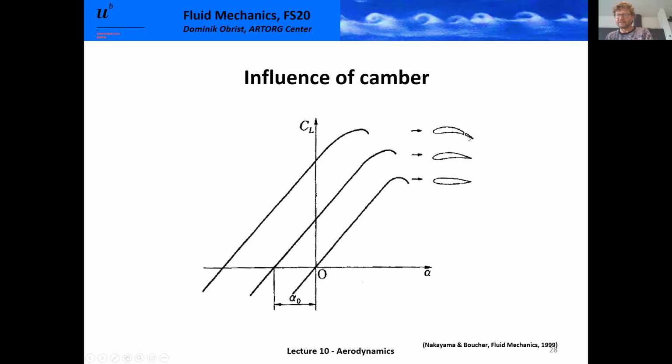And the flaps here, you can see them in commercial airliners. If you sit above the wing and look out at takeoff and at landing, they will put out the flaps, and it's not so much to increase the size of the wing, it also does that, but in the first place, it increases the camber. They put out the flaps to increase the camber to locally increase lift. It will also increase drag, but at takeoff and landing, you mainly want to maximize lift.